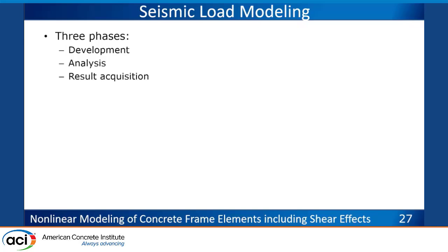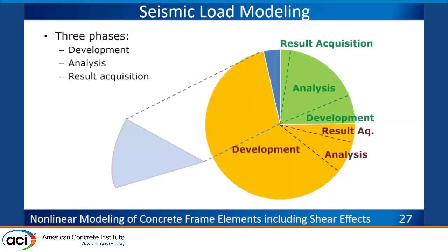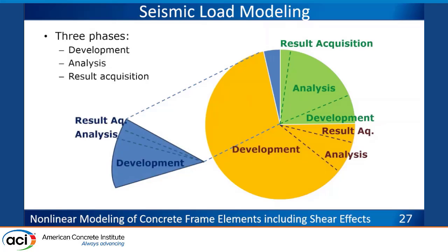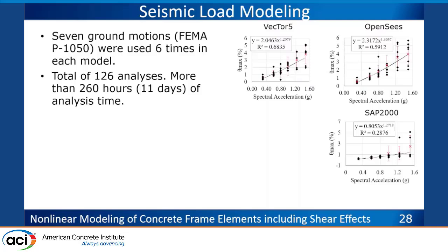Seismic load modeling, you need to do incremental dynamic analysis and analyze the results. My student spent a lot of time to see how much time it takes to do all of these. He considered 7 ground motions 6 times. This is what I meant. It's not a single analysis, but you need to go through these analyses, totally 126, more than 620 hours, 11 days of runtime. This is just the software running, even when you use something super simple like this. So we are talking about significant time still.